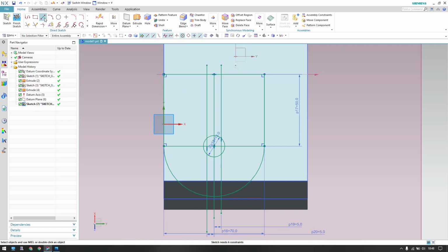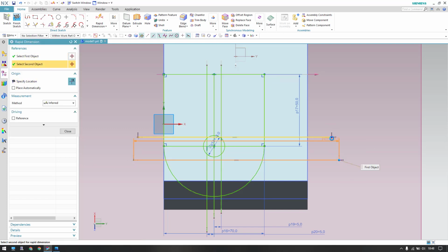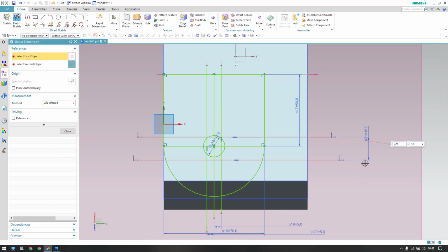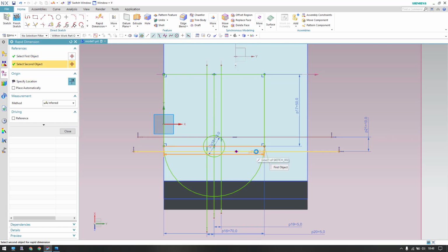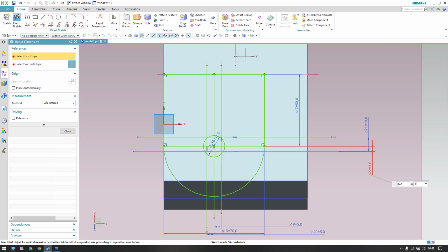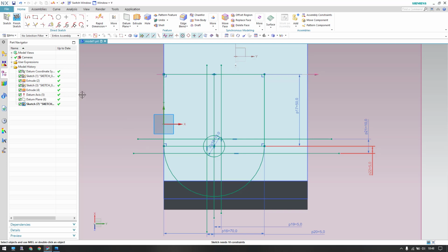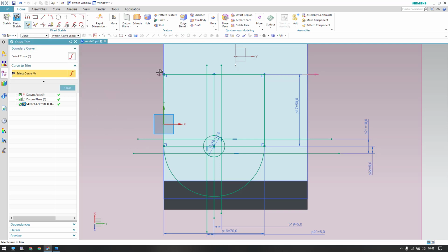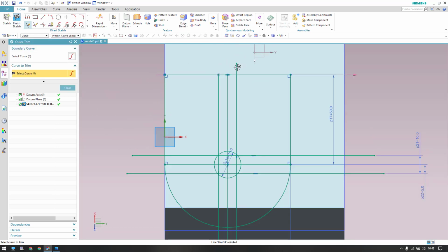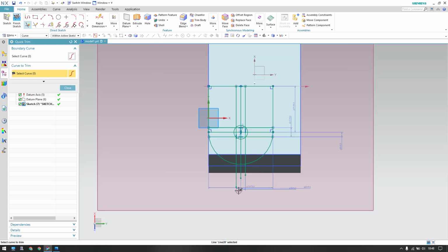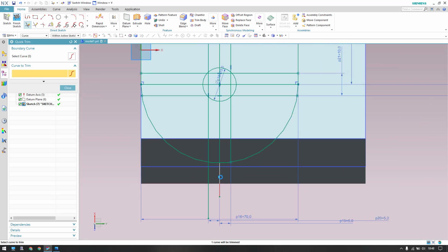Okay, so now let's draw here the lines, and these two lines should have dimensions. Between this to this it is 10 mm, and between one edge it is 5 mm. Okay, so now let us trim this with that command T. So I'm just going to trim these extra portions. Okay, and we also have this here.